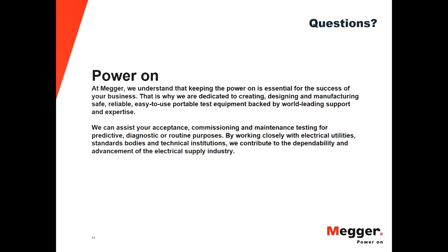If I had to talk about impedance testing versus capacity testing, both look at two different things. Impedance testing is a check of the electrical path in the system. So you measure the impedance of the cells, you measure the resistance of the straps connecting those cells, you measure the DC voltage. So you basically get an idea of the condition of the electrical path.